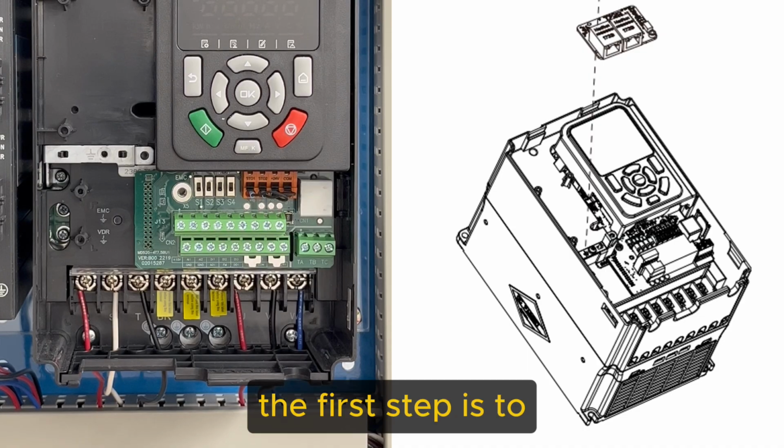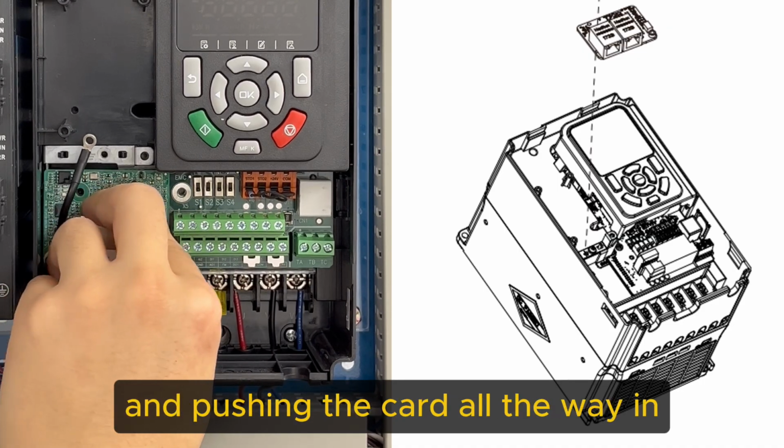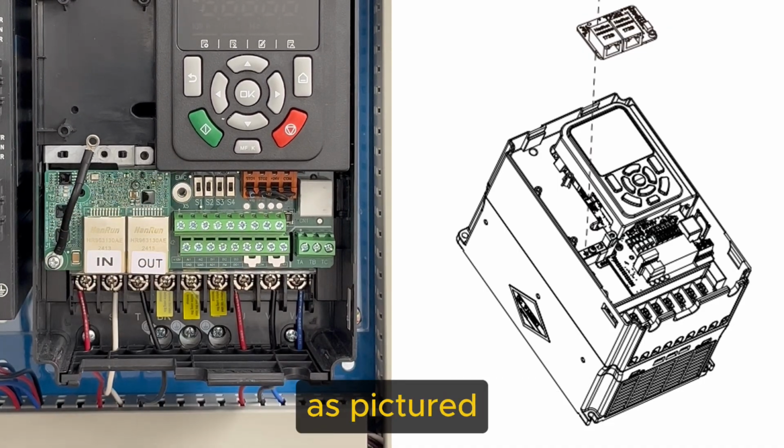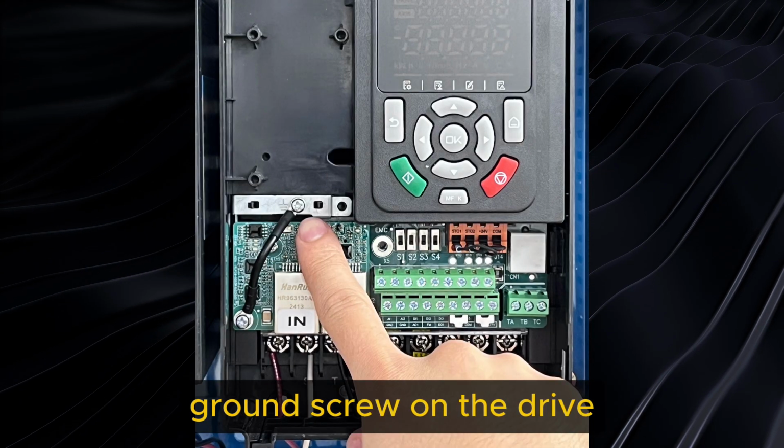The first step is to install the expansion card by lining up the pins to the terminal block and pushing the card all the way in as pictured. Next, screw in the support screw and connect the grounding pin to the ground screw on the drive.